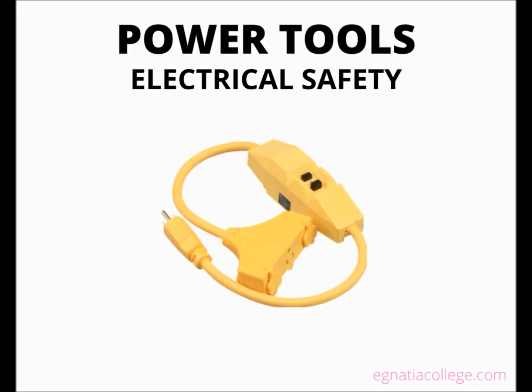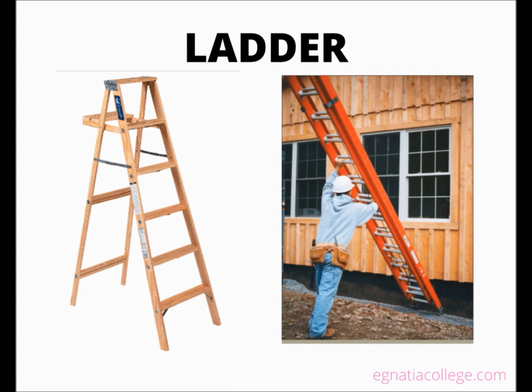Power tools. Power tools increase productivity for specific tasks as well as entire projects. Electrical safety. Electrical power tools are connected directly to a power source, so they should never be used under wet conditions. Ladder safety. Working from a ladder may expose you to serious injury or death. Using power tools while working on a ladder increases the risk.